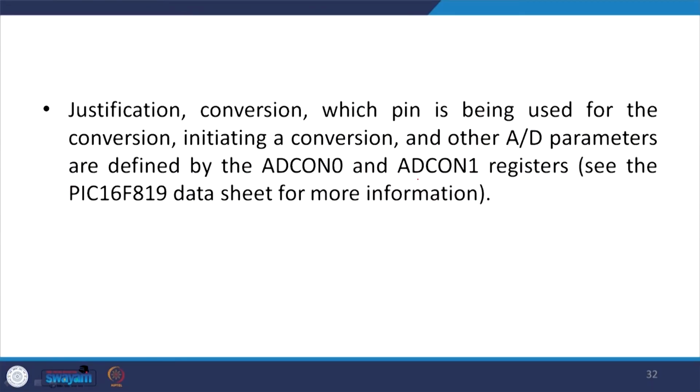Justification, which pin is being used for the conversion, initiating a conversion and other analog to digital parameters are defined by the ADCON0 and ADCON1 registers. Okay. You can see further in the data sheet of the PIC 16F819. Then the last and final stage of this mechatronics design is build and testing of the system.